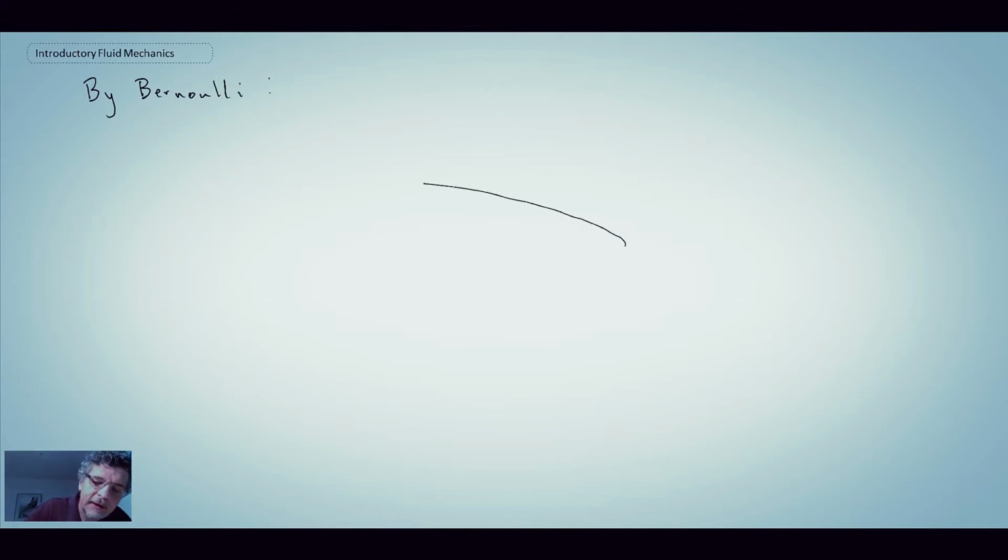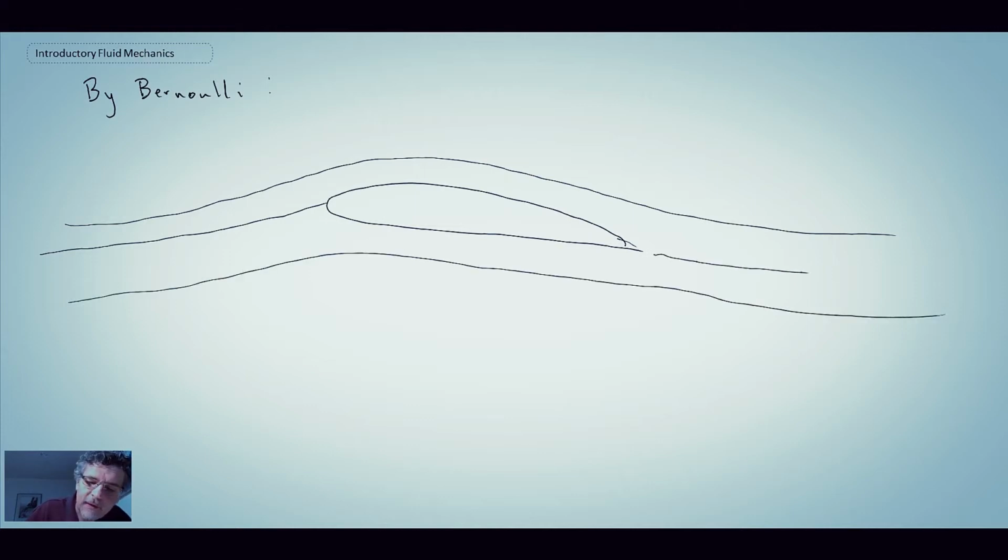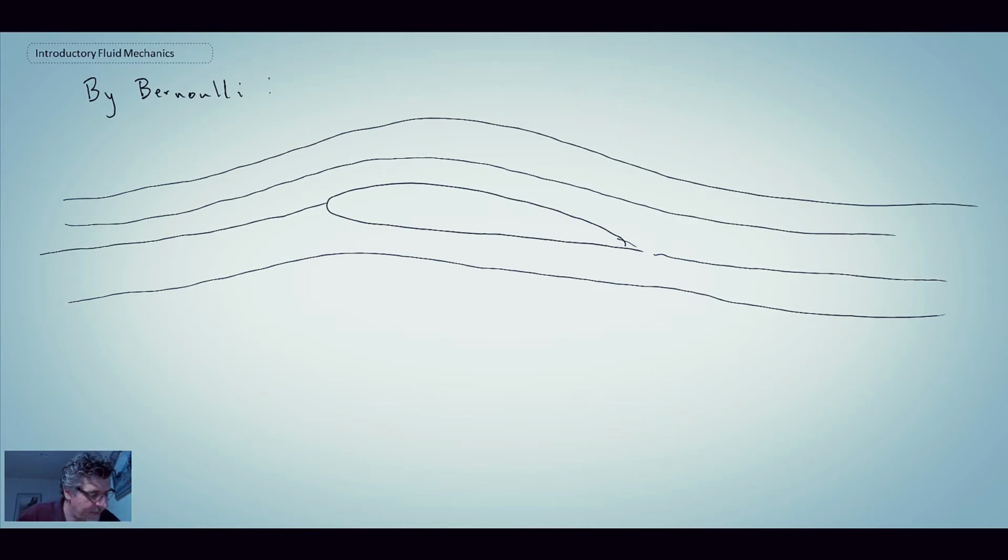So with that, and looking at what we know in this course, through Bernoulli, and looking at our airfoil section, what we saw in the video, we saw the flow coming along, the stagnation streamline coming up over the top, and then a streamline coming off the trailing edge. But what's happening here is the upper region has a higher velocity. There are a number of different ways that you can explain that. Some people say that the fluid has to take a longer path on the top.